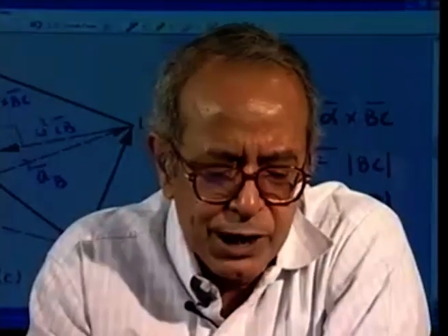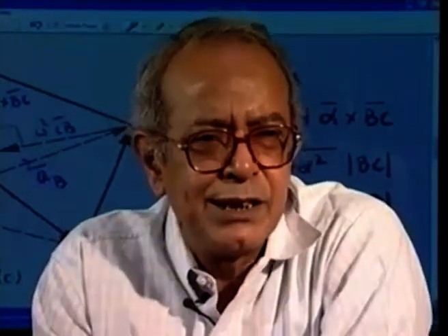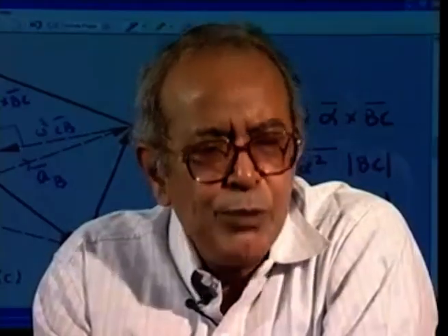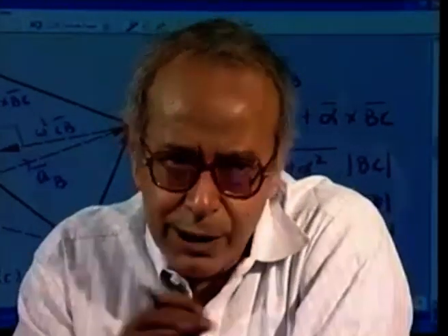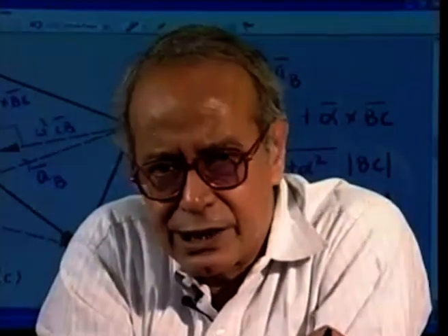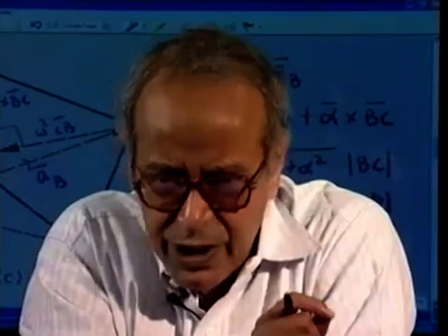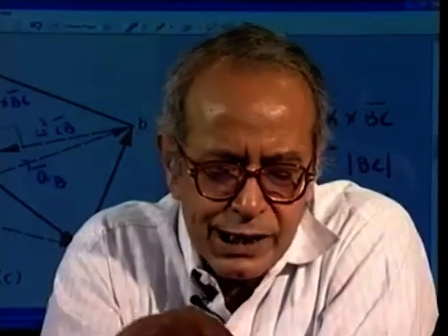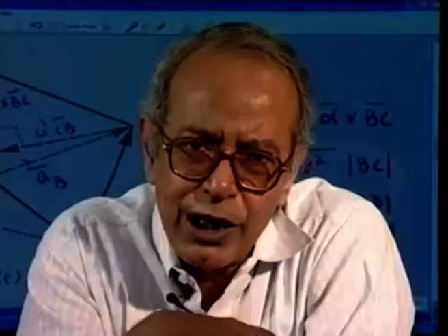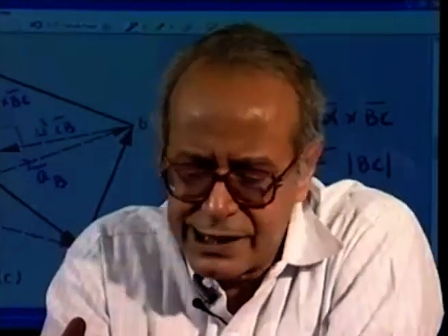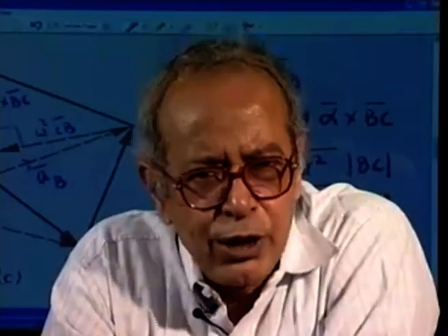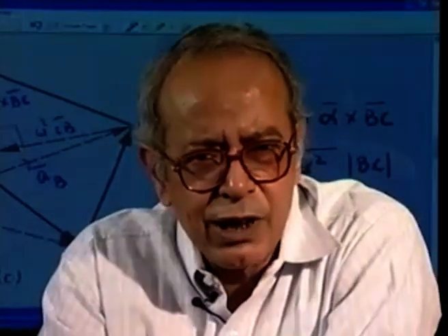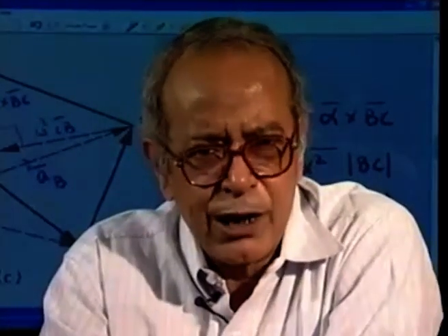Then we have also developed a very useful concept like velocity and acceleration image, which will be useful for mechanisms having higher order links. What do you mean by image? If we use the same convention of using small letters for the velocity and acceleration diagrams and capital letters for the configuration diagram, then for a particular rigid body, the velocity diagram and the acceleration diagram give us a scale drawing of the original higher order links. The scale factor is omega for the velocity diagram and square root of omega 4 plus alpha square for the acceleration diagram, where omega and alpha are the angular velocity and angular acceleration of that particular higher order link.